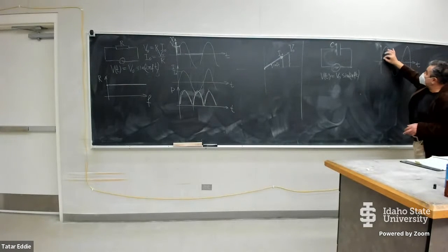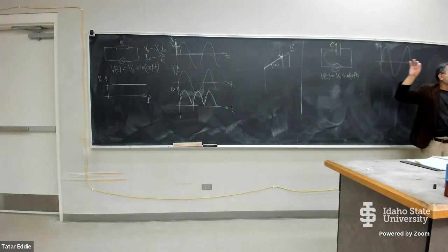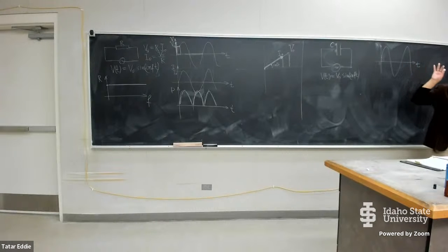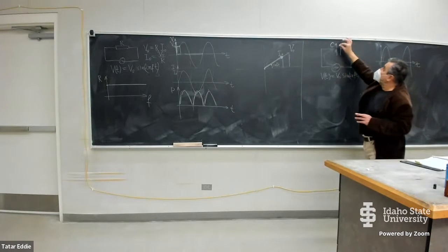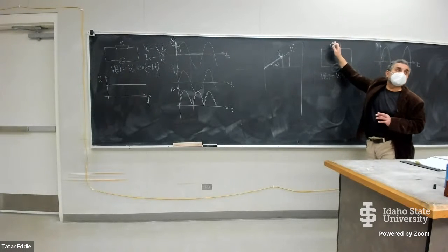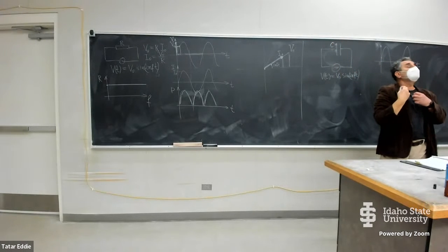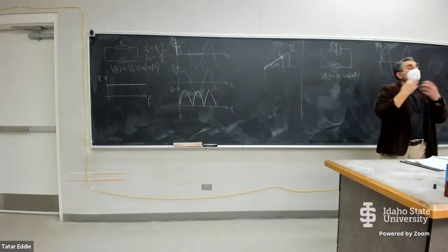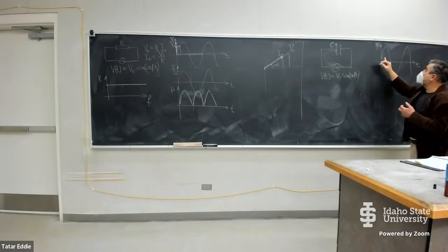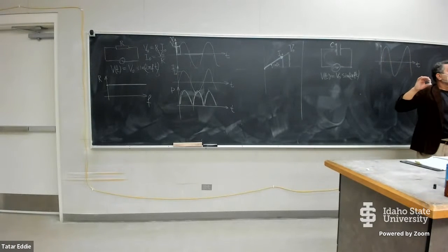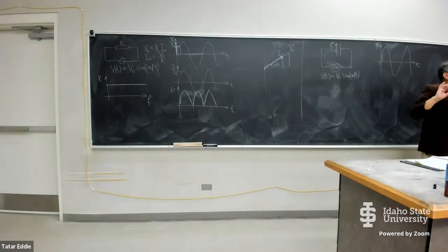Well, at the next moment of time, the voltage is higher, but those charges have harder time making it to the capacitor because you already have positive charges piled up here and they're going to repel the newcomers. They don't want newcomers to come close to them. So even though you increase the voltage, the charges don't move so easily, so the current doesn't increase as you expect.